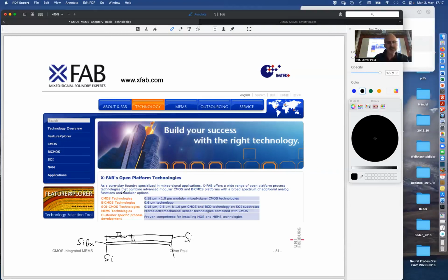So then maybe there is a trench etching that separates one transistor from another transistor, which can have various advantages. So the transistors are in really separate wells, not in the kind of wells that we have seen before that are adjacent to each other. And that solves a lot of problems, like signal transmission across transistors and latch up and electrical problems of all kinds. And so this is a way to do it. They also have MEMS technologies.